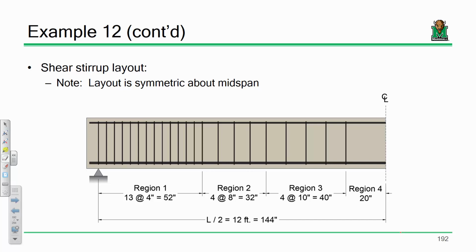You'll also notice with shear design, you tend to use tighter spacing near the supports and wider spacing near the center. And that's because that's what shear diagrams look like. If I have a simply supported beam and a uniformly distributed load, the shear diagram looks like that, right? I have higher shears near the ends, very low shears in the middle. As a result, near the middle, I don't really need that many stirrups. And there will be a region near the center where no stirrups at all are required. But we'll get into the ACI requirements of that as we progress. Does everybody have this?